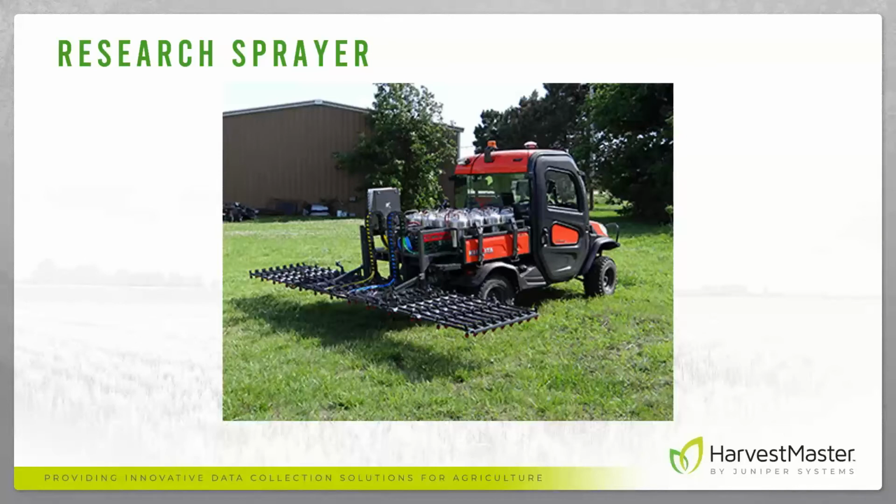You go in and make some changes so that, you see, the first boom has a slightly different position from the last boom, and so we can make that adjustment using the GPS and create an offset so that each boom starts at the same plot as you go into the next plot.